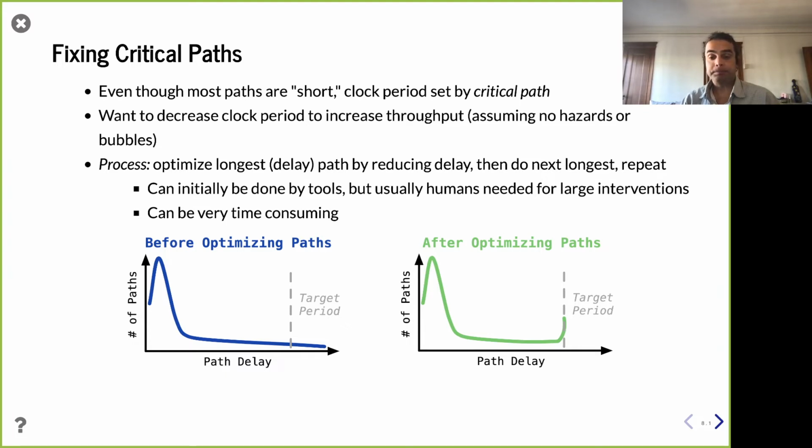And so you can maybe sometimes meet this clock period, right? But then you're going to do so in a way that perhaps has a lot of bubbles. A lot of times your design can't do anything useful, in which case maybe it's not worth it, right? And so there's a lot of caveats to this, but some key takeaways from learning about this kind of optimization of critical paths is that people talk about, where does the effort go in hardware design?